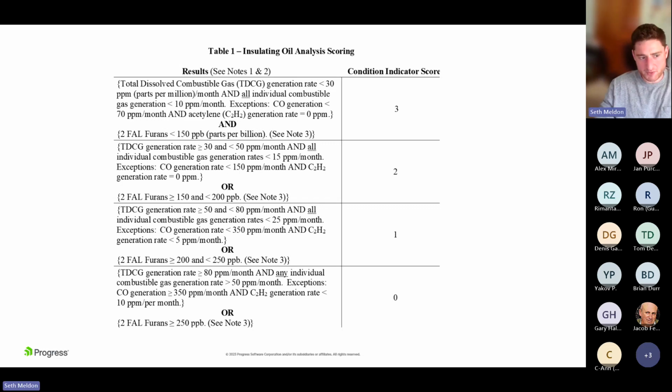So now we add into that, this is one of those where there is a calculation to be done here. There's a right answer based upon this combination of values. But now we add into that, besides just these observable gases being produced, we can move into things that are even more convoluted, like specific test measurements. Obviously, in here, we also see things combining data from the last time we checked this transformer versus the nameplate, in addition to what the difference is between now and the nameplate, and what the difference is between now and the last time we checked it.